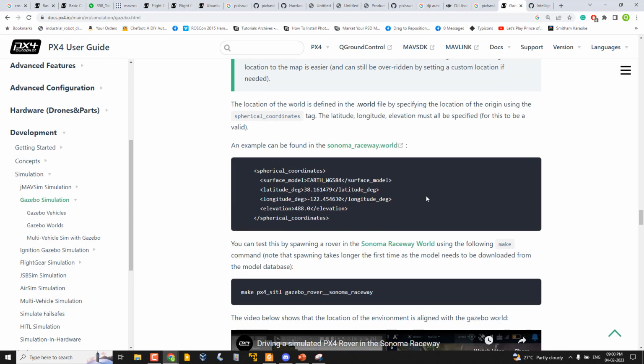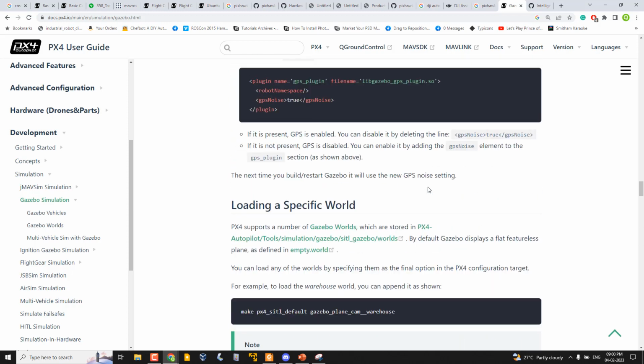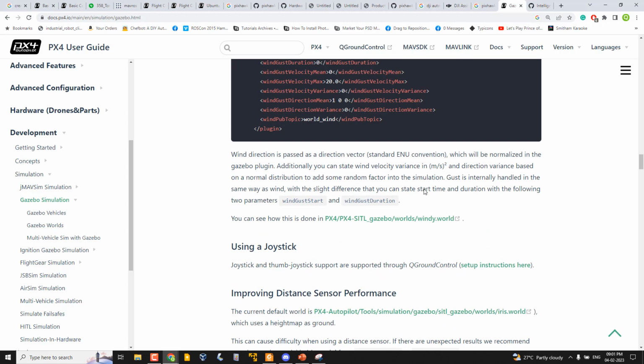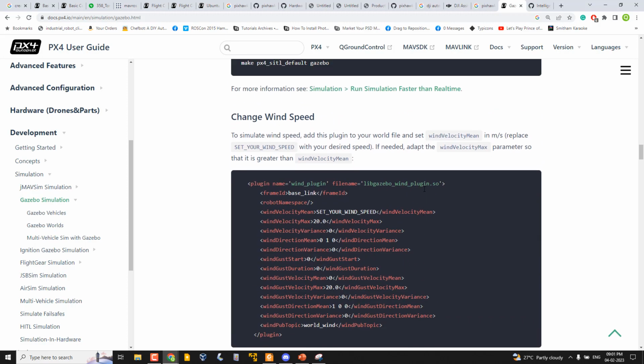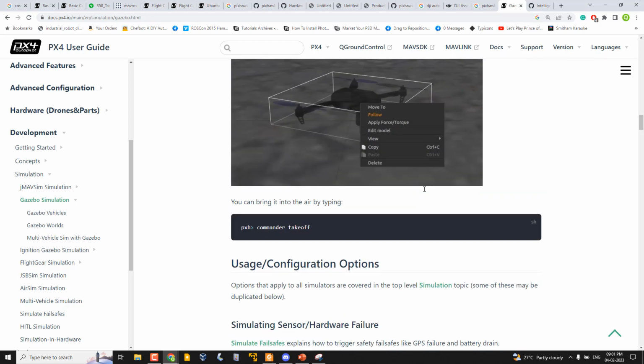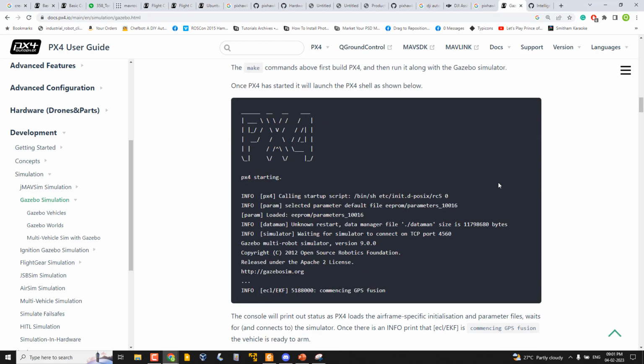Mostly, if you work with the Gazebo simulator, even if it is a drone or a mobile robot or anything, the easiest way to add multiple robots is by changing the namespace in the controller. You can easily add multiple robots.